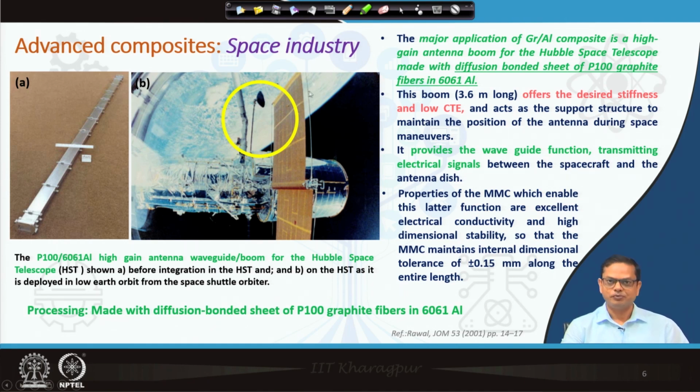Okay. So, again you can see that there is no other composite material or other material which can be used here. That is why graphite, it shows very high strength, high modulus. If you can make graphite fiber or carbon fiber at a high temperature, it shows extremely good strength and modulus, and those can be used to make this kind of aluminum graphite composite material.